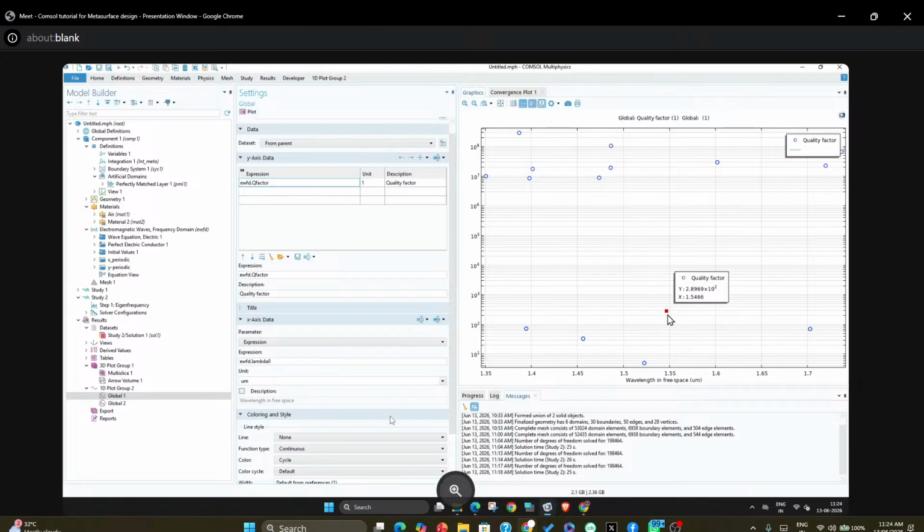So I will show you the transition at this mode, which is 1.5466. Now, how to calculate the transition. This is the part here, the eigenfrequency analysis type of things you can do for your simulation, and you can find initially what is the resonance frequency of your metasurface and all these things.